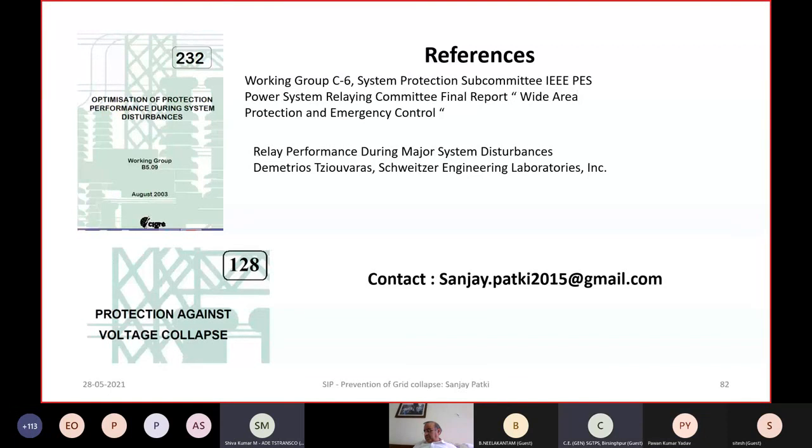At present, on distance protection for power swing blocking, we are allowing a trip in zone 1 and blocking all the remaining zones. And we are not keeping any out-of-step protection. In this case, if the circuit breaker opens in zone 1, then there is a possibility of circuit breaker failure, sir, because of the high voltage angle between the receiving and sending end voltages.